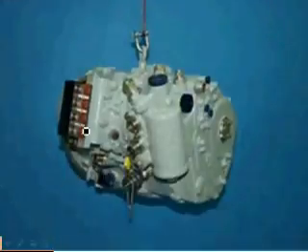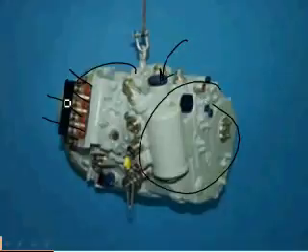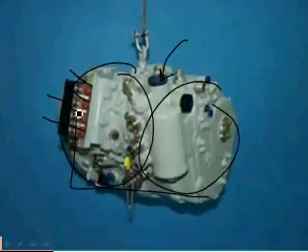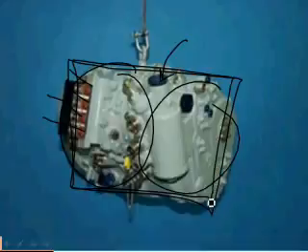And there's a picture. You can see the wire attachments for the generator, and here's where you add fluid to put into the CSD on this side and the generator on that side. But it's one chunk. You can't take both parts out of it separately. You've got to take the whole IDG out of the airplane if it needs to be replaced.